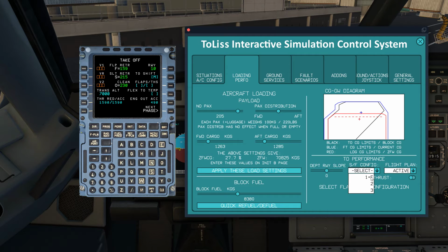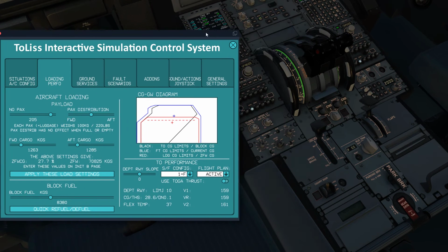So I believe we will be able to take off with flaps 1, right? Yeah, perfect. So we go flaps 1, and here it automatically calculates V1, VR, and V2. So you pretty much just dial in those numbers into those windows. Perfect. Flaps will be 1 slash down 0.1. After we push back, we will simply select flaps 1.